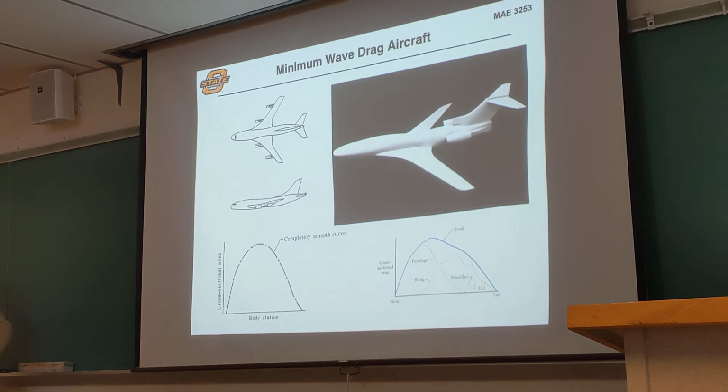So winglets are essentially a fix after the fact. If you've done your airfoil and wing design correctly the first time around, you don't have to worry about it. It does give you an effective increased span when you go through that process. You are boxed into a particular span at an airport terminal. They won't let you increase your span because it's designed for a 737. So adding winglets is an option to try to improve your overall performance.